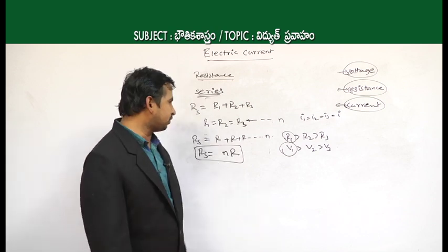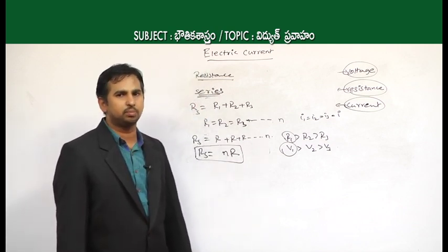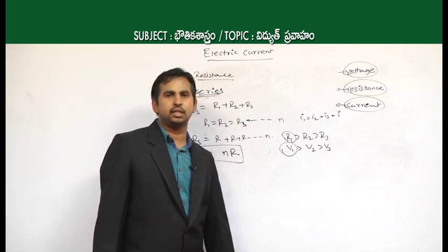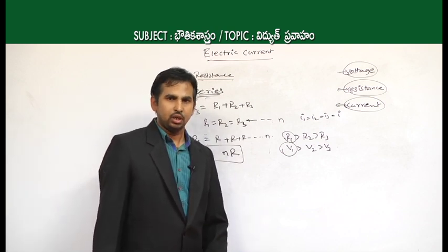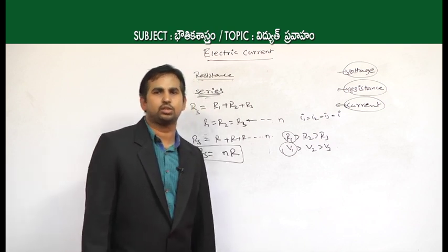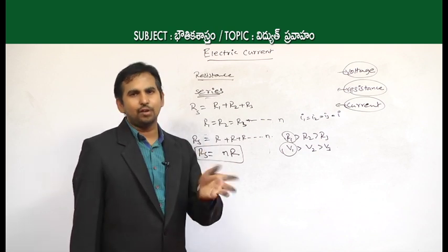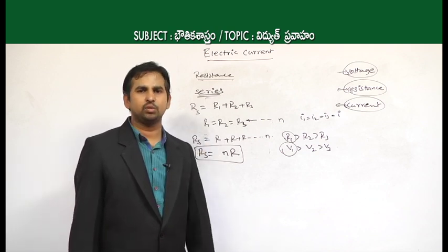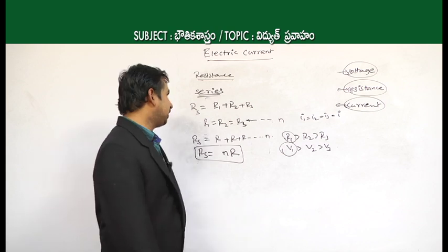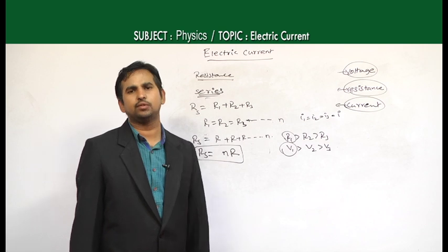So, that is why in most cases of resistances in series, we observe it in bulbs connected in series, in the case of decoration bulbs. In these decoration bulbs, the same amount of current passes through all of them. So, if you switch off one of the lights, the remaining also go off. That is the application of a series connection.